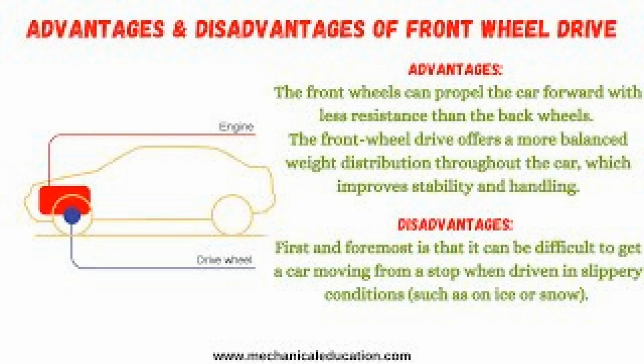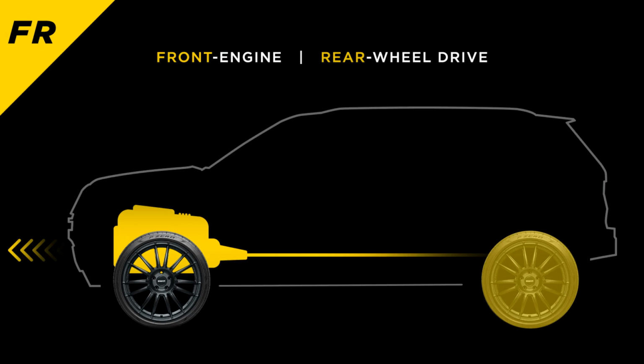Controlling the vehicle on slippery road surfaces, wet, snowy, leaf-strewn, etc., requires some skill. Due to design features, a rear-wheel drive vehicle is prone to oversteer. Careless handling of the accelerator pedal can cause the car to skid. It is worth recognizing that both front-wheel drive and all-wheel drive cars have their own peculiarities in driving. Therefore, even if you do not choose rear-wheel drive, be sure to read how to cope with a skid.